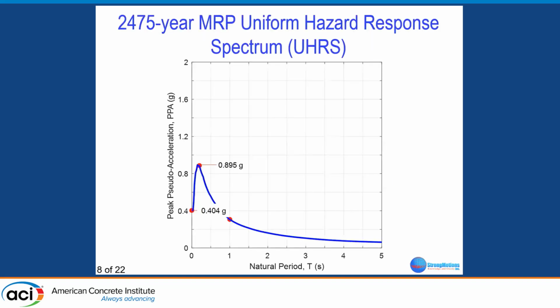So we can plot them. They are shown here, in the form of a response spectrum. These red dots are the 3 values provided by the USGS. And like I said, if you are outside the country, then you will use the values provided by other authoritative agencies, who are supposed to do the work of the geologists and seismologists, right?